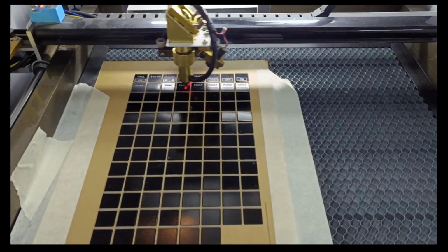After that you have to laser engrave. So I put it back into its original cutout, but then change the mode to engraving the letters or the markings here. Once you cut it, don't pull out this tape. Just let it sit there, because if not, you have to realign again. Then put the painted one back into the cutout, the hole that was cut.